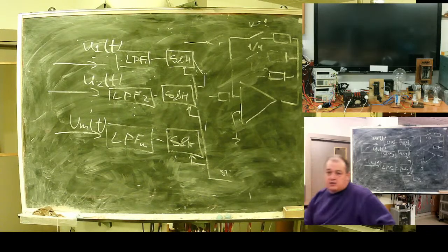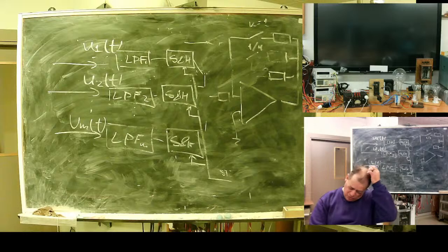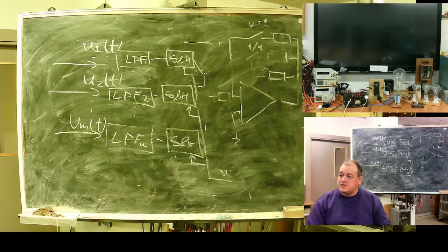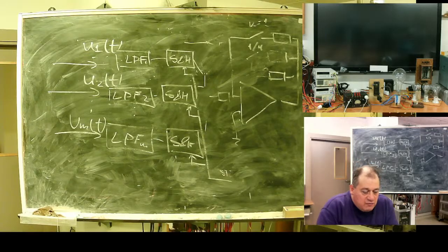Output, there are two approaches. One is to isolate at the moment, you know that one of the tricks you can use isolating amplifier as PGA. But it's not a good solution. Because isolating amplifiers use modulation, demodulation, what you will get? You will get transients on every gain change. It's not a good solution.